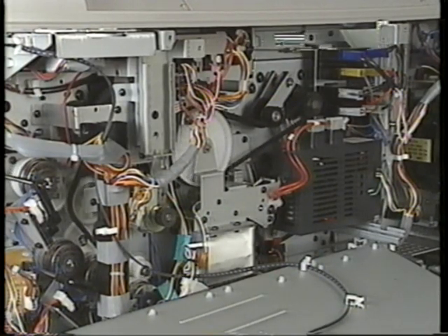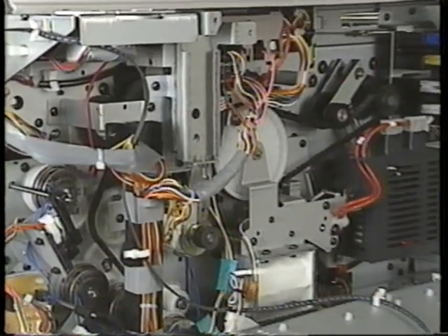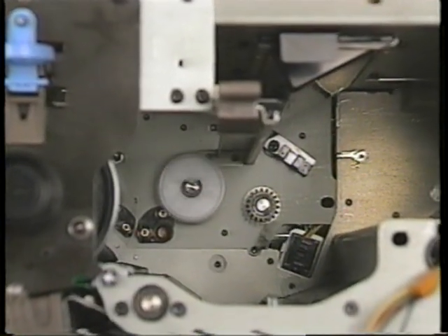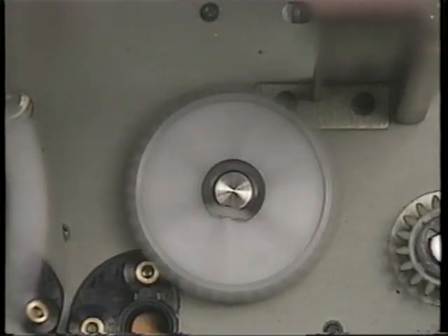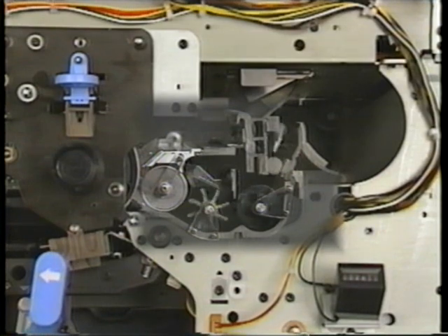In a desktop copier, the moving parts in the development system are driven from the main motor by a system of belts, gears, or both. Typically, motor drive is transmitted to one gear on the back of the development unit. This gear engages others on the unit and transmits appropriate rates of rotation to all the moving parts in the system.